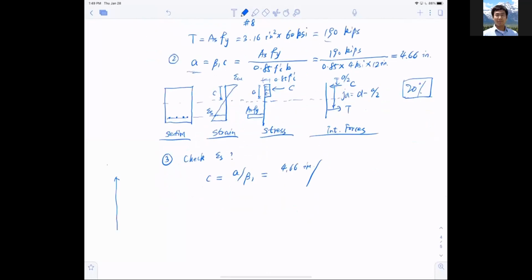So draw the drawing. This is f'c, this is 4, this is beta 1, and by the way, this is the ksi. I'm just going to put this unit here, for f'c in ksi. And beta 1 equal to 0.85 down to 0.65, and a straight line in between. Now we have f'c of 4 ksi, right there. So beta 1 immediately equals 0.85, clear as day.